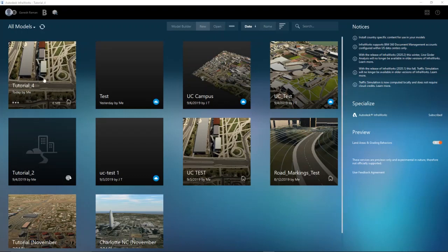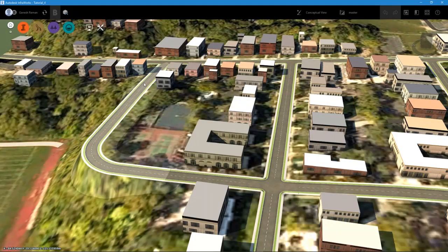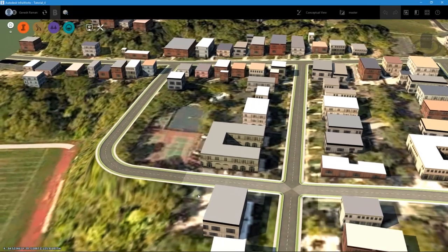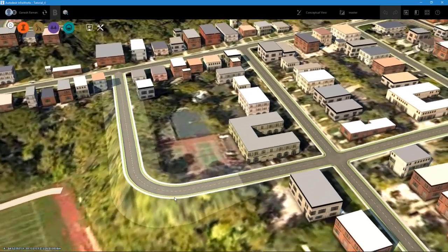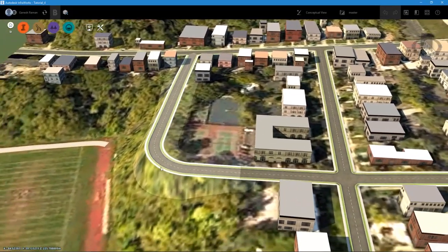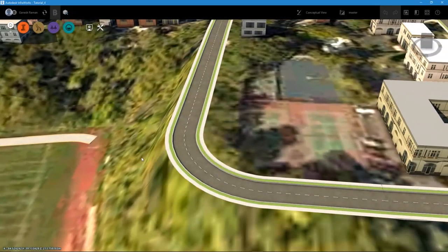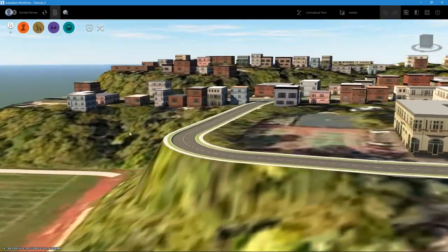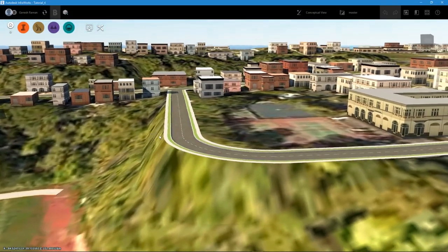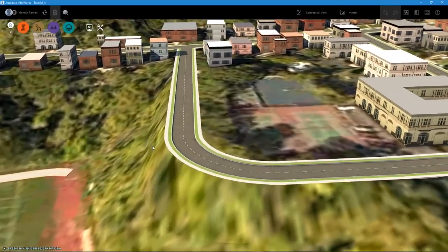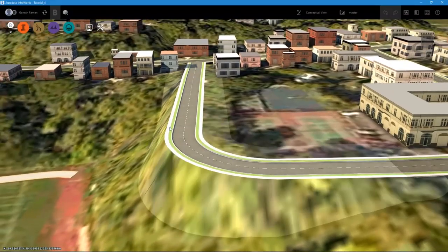In the previous tutorial, we created a road to connect Austin and Jocelyn roads. In this tutorial, we are going to look at how to replace the components of a road that has been built. So in this case, I can see that there is a big slope, or the steep slope rather, on the edge of this road. So it's probably not safe to have a sidewalk here. So I would like to replace this sidewalk with a barrier or a median that will help keep the